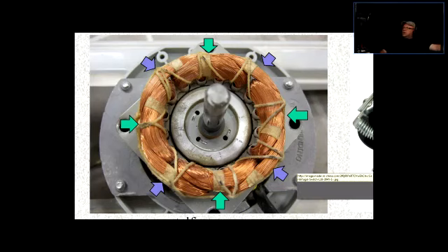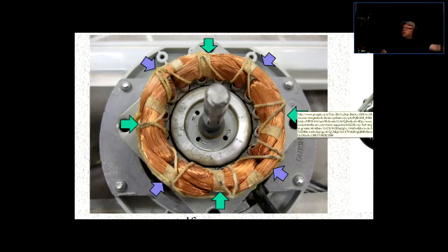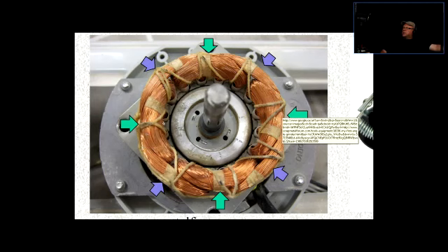And look, how many poles do we have here on the main winding? We have one electromagnet completed and the other electromagnet. So if one is north, the other is going to be south. So we have 1 and 2 poles, 3 and 4. Right? So we got 4 poles here.